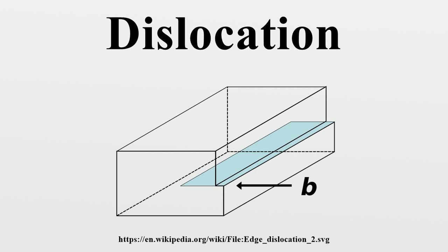Edge dislocations. An edge dislocation is a defect where an extra half-plane of atoms is introduced midway through the crystal, distorting nearby planes of atoms. When enough force is applied from one side of the crystal structure, this extra plane passes through planes of atoms, breaking and joining bonds with them until it reaches the grain boundary. A simple schematic diagram of such atomic planes can be used to illustrate lattice defects such as dislocations.